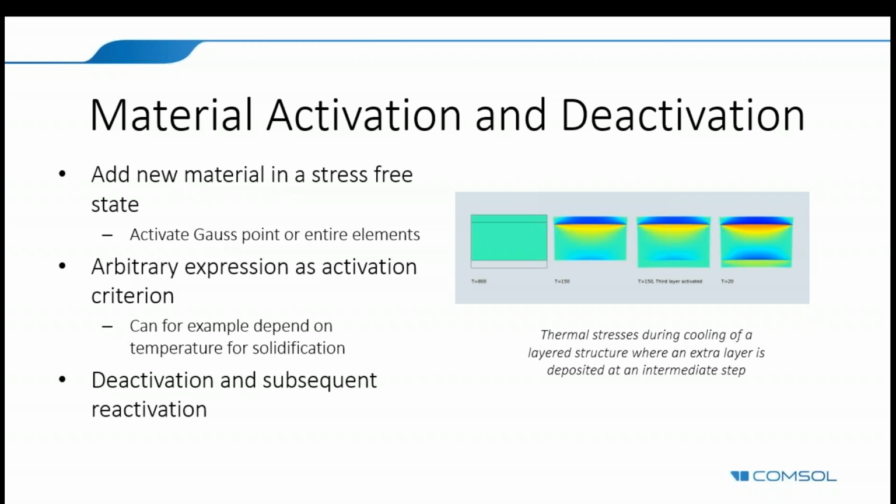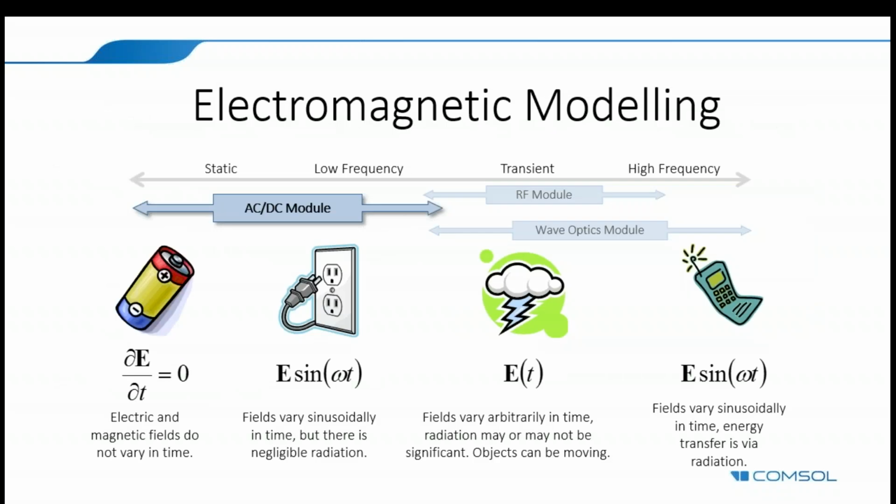So you can compute the transfer of stress correctly from the existing material to the new material that's being deposited. This will often be driven by the fact that the material is deposited at a high temperature, and the different layers are contracting at different rates as they're cooling.